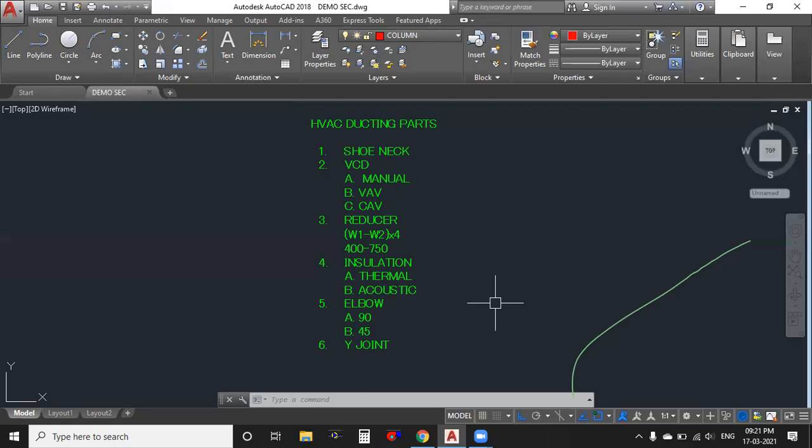Usually the silencer won't come in HVAC. That is to reduce your sound. It is included in HVAC, but most probably we are not going to use that one. For that, we are going to use canvas cloth, because that one is too expensive, right? Actually, we have used that CTS in our recent project. That's why I asked. In my experience, I have not used CTS up to now, because we keep our equipment somewhere and distribute ducts in some other place. If you are using a CSU, the unit will come below 10 tier only. In 10 tier, you won't get that much noise. So if you use canvas cloth, that's more than enough.